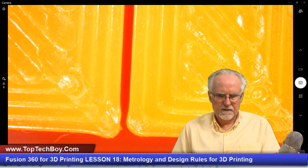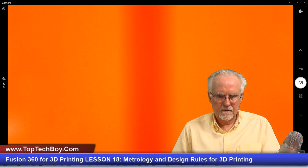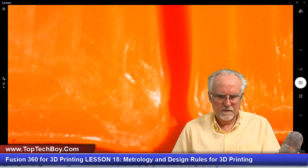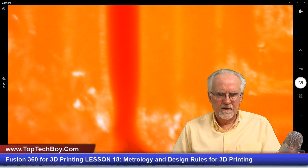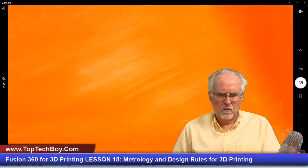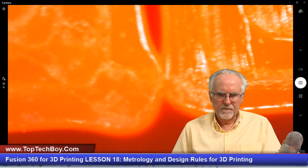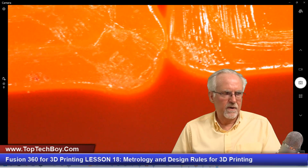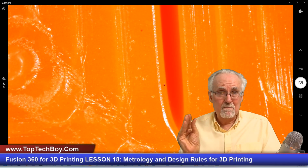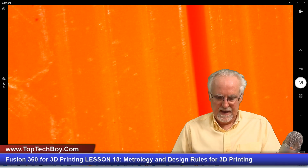And so let's come back here. This is our 0.2. Let me see if I can switch over to the high magnification. Okay, there is our high magnification. And come down, and you can see definitely I'm having a problem at the corners. Now let's go to the 0.1 millimeter gap, and you can see at 0.1 millimeters, I'm actually getting bridging occurring at the corners. If I'm bulging 0.1 millimeters at the corner and I have a 0.1 millimeter gap, then I am closing that gap on the corner.